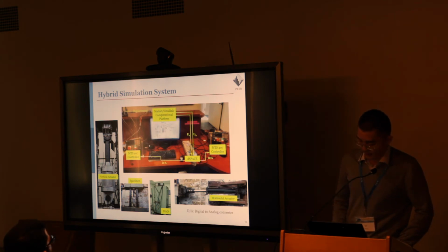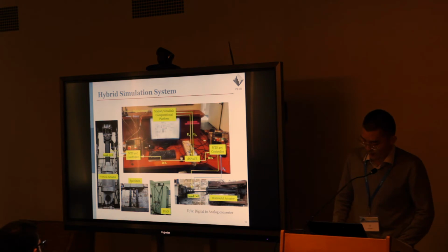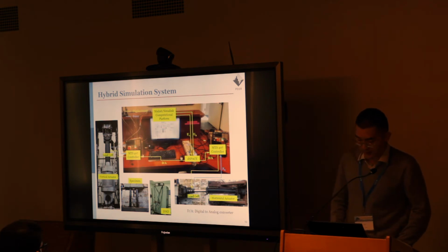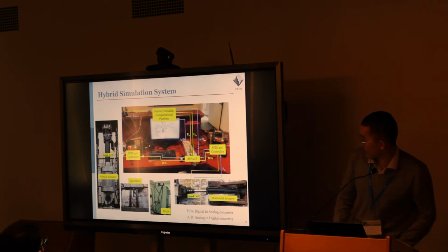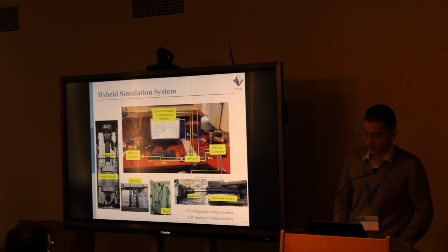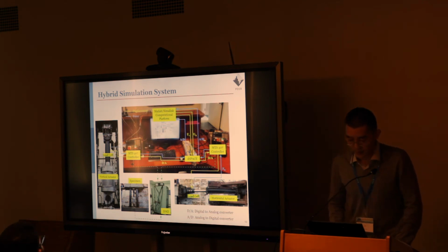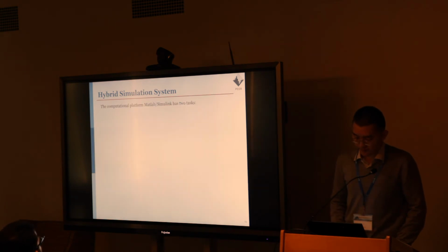And after applying the computed displacements to the specimen, the corresponding resisting force was measured by the load cells inside the actuator, and then the analog voltages representing the force were converted to digital force values before they were passed on to the time-stepping integration algorithm to move our solution to the next time step. In addition, a data acquisition system was used to collect data from different experimental instrumentations.